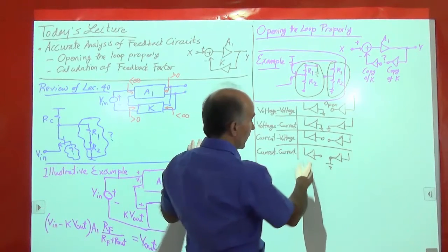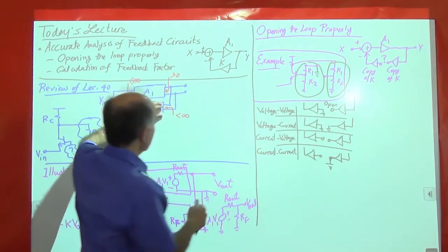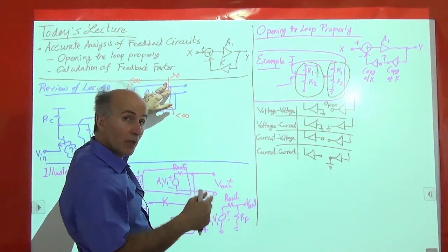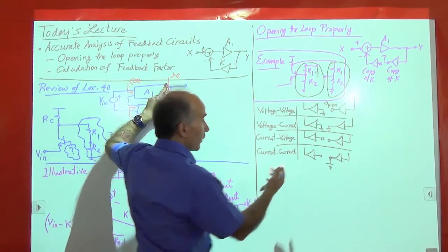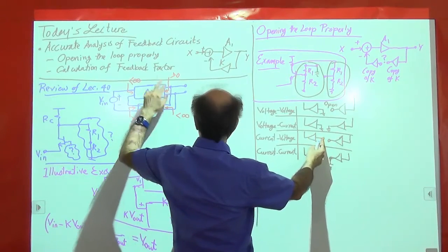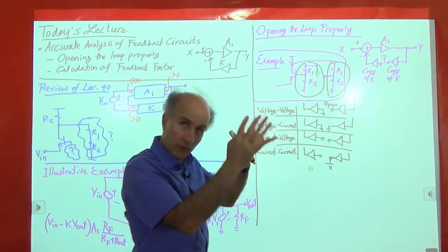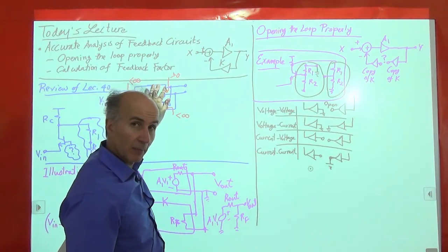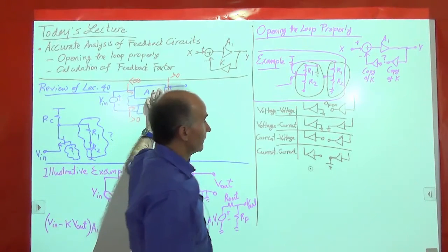Similarly, when I am sensing a current, if this circuit is sensing a current from here, the output impedance of this guy is very high. It's trying to generate a current, right? It's like a current source. So when I want to take this in isolation, when I want to disconnect it from the amplifier over here, I leave it open to represent the fact that it was driven by a high output impedance when it was connected to the main amplifier. All right? And so on.